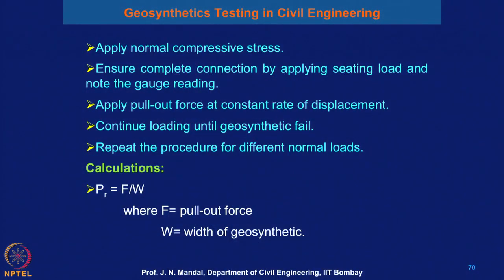So, from this test you can calculate the pull out force per unit width, that is P_R. That depends on the pull out force, F, and the width of the geosynthetic material.